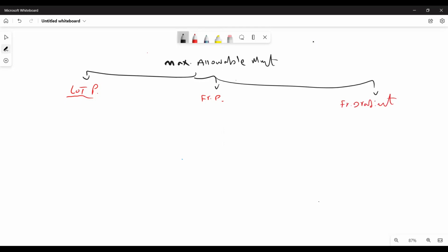Okay, so if he gave us leak-off test pressure, we need to calculate the maximum allowable mud weight as follows. First thing here is to put the mud weight at test plus leak-off test pressure, as discussed yesterday, leak-off test pressure over 0.052 times the TVD of the shoe.